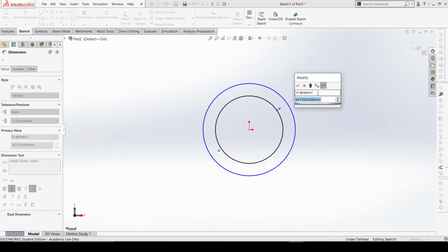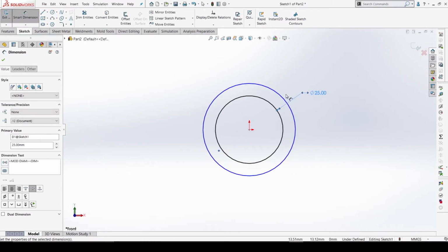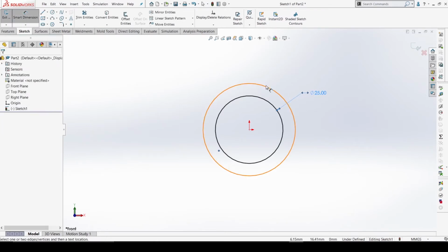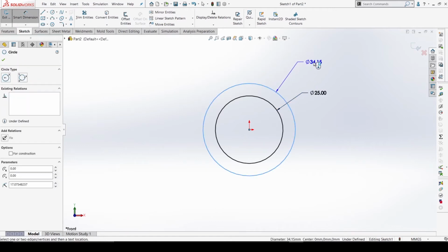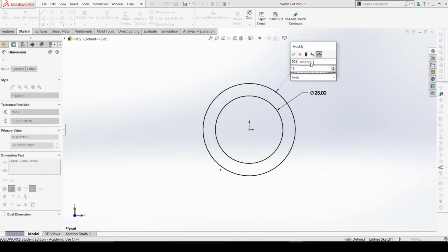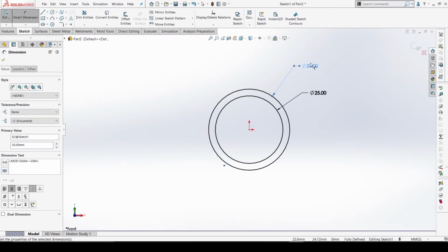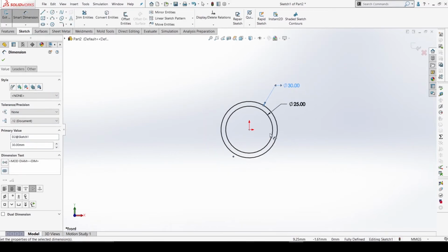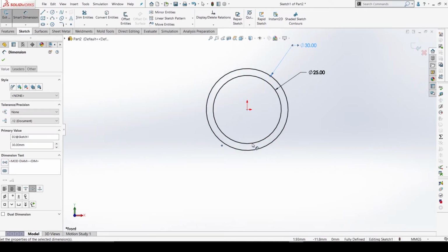How did I take this? I used the mouse gestures to take the diameter. How is that? You have to right click and drag up. I've told how to set those up in a previous video. So it's a radius of 15, so diameter is 30. When the circle is not complete in the sketch, they usually dimension it with its radius.